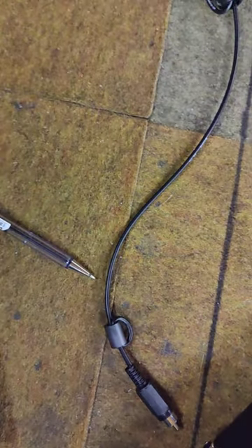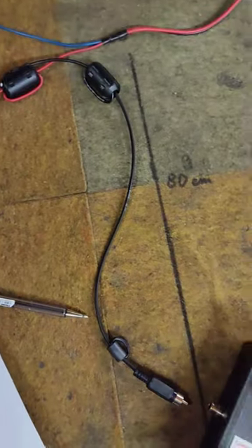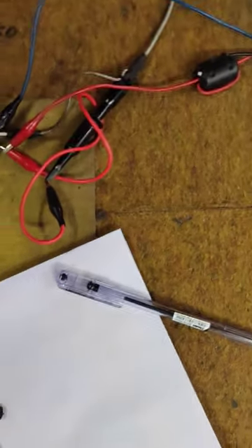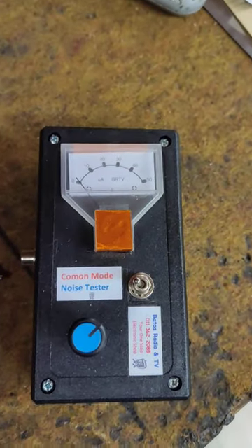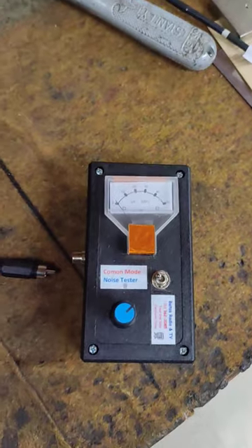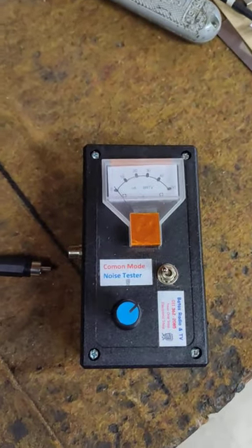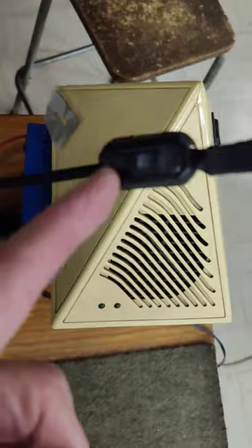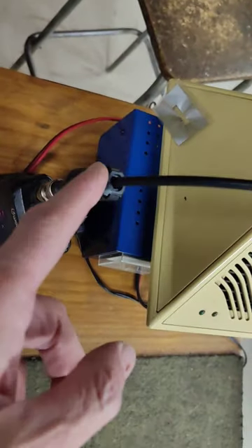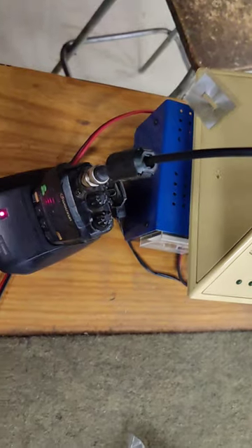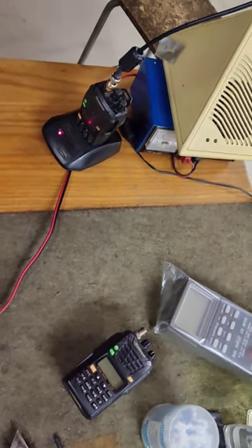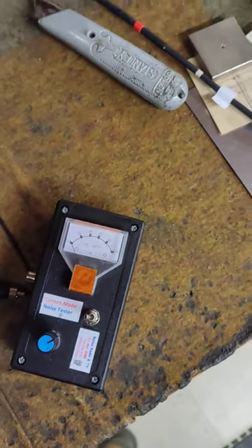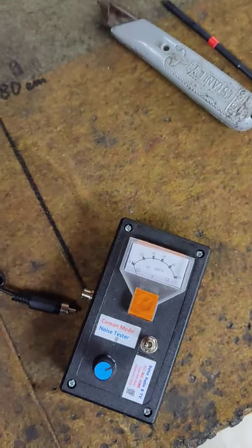It will help you if you do pick up noise even on audio cables, wherever you got the noise problems, you can try and use the instrument and see whether you're solving the problem, whether you're fitting the filters at the appropriate places, like even on this particular antenna. You can actually see now this and this sort of clip-on ferrites are placed at specific positions. And why at specific positions? Because the instrument told me so. I could actually see by moving the ferrite up and down where is the biggest attenuation that I'm actually obtaining.